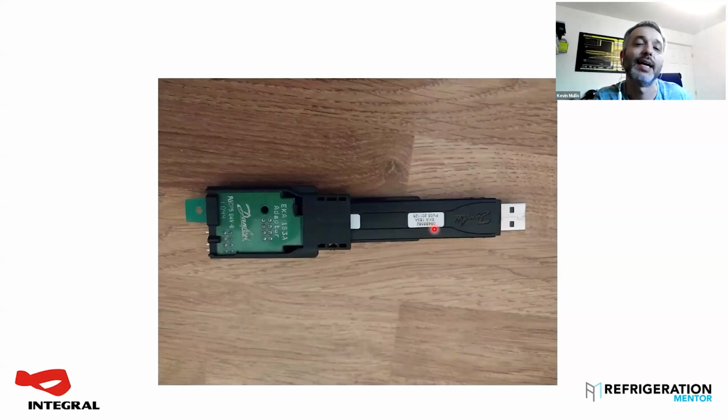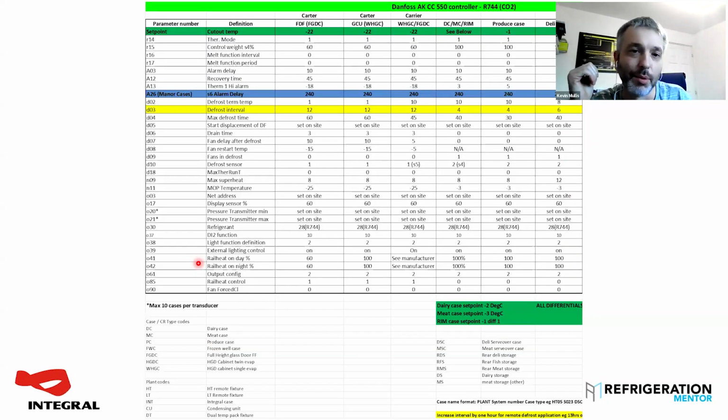It's an absolute massive labor saver if you're setting up loads of cases. All you need to then set is a parameter called 003, which is the LON address, which is how the front end panel identifies it. And you can then see your parameters on the front end, and that will make your life a lot easier. EKA 183, that is, you can Google that and find one to buy on the internet.